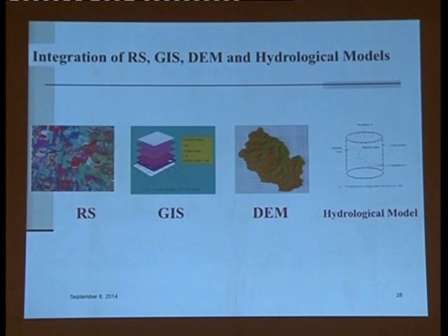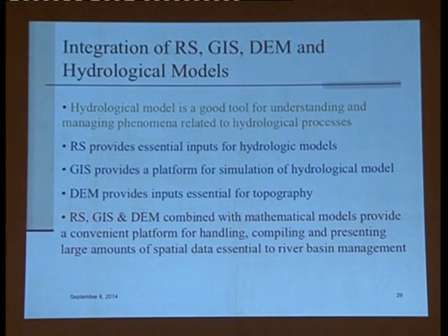Now, that forms a major input as far as any hydrologic model is concerned to estimate the stream flow in a river basin. But that's as far as climate variables are concerned. In addition, we also require the land use, land cover change, the drainage pattern, and other information to give to a conceptual hydrologic model. So there are many hydrologic models available which consider the climate information, land use, land cover information, and so on and so forth to get us the stream flow at a given basin.